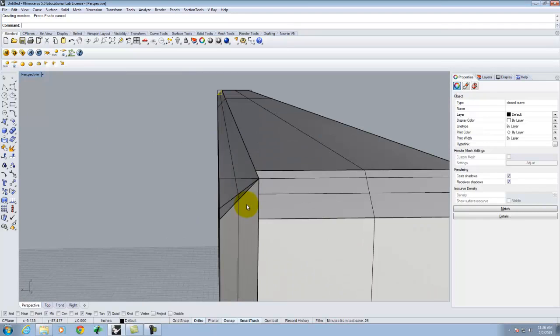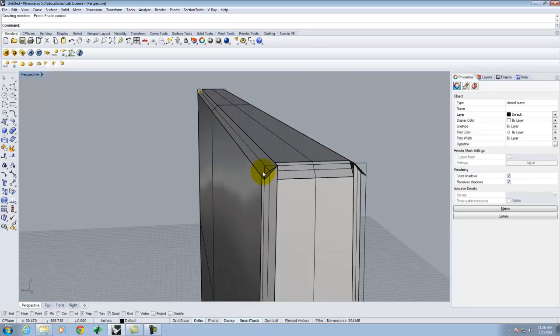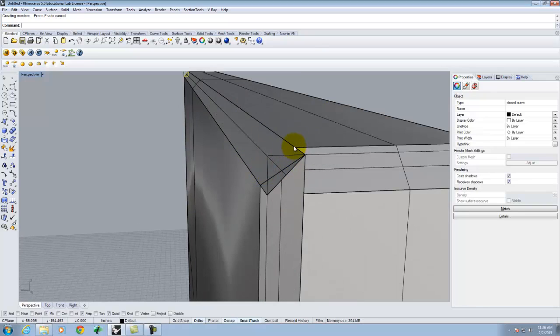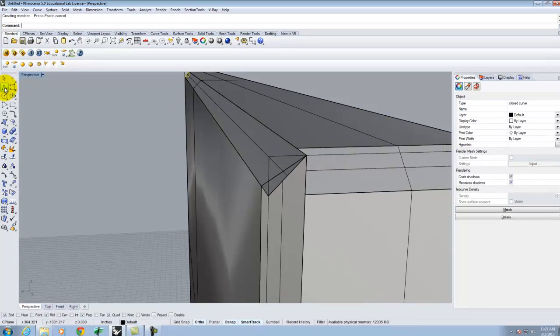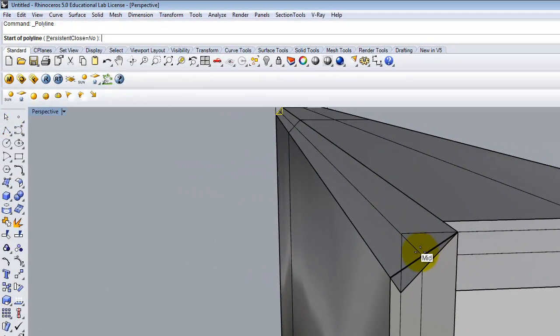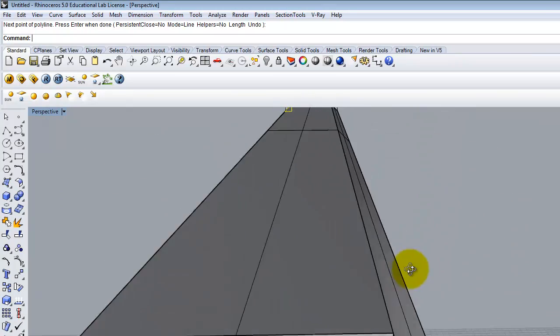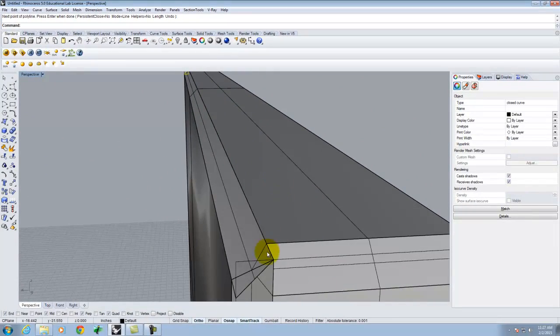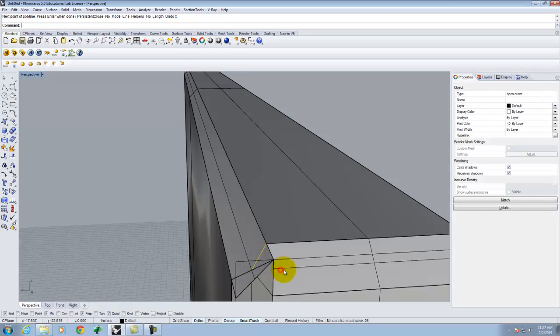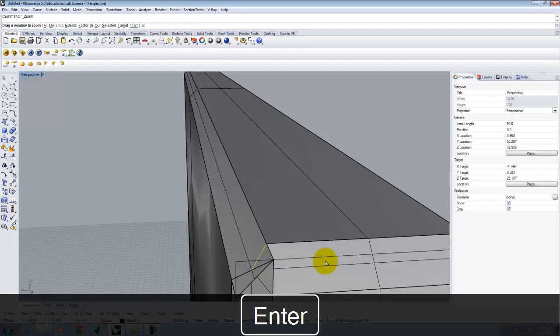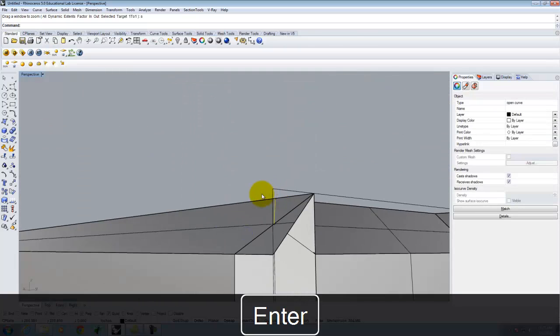So if I was unhappy with having that triangle as my view, I can actually do this slightly differently. I could use my polyline, right? I could go to the midpoint of this, and I could draw a line back, a line down, and a line back this way. Okay, now here once again I'm in that zooming problem, right, where I'm not centered on the view anymore. So let's go ahead and select one of those curves. I'll type Z for zoom, S for selected, and I'll recenter my view around that.